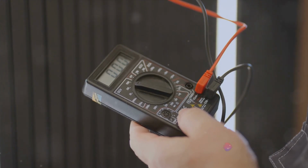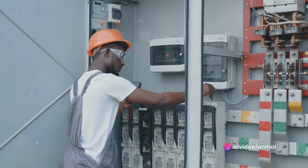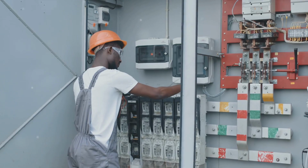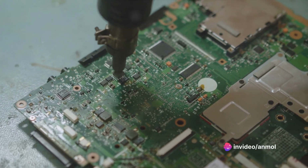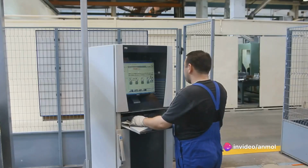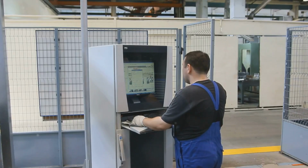Phase 1 put a spotlight on preliminary checks and the use of a multimeter to measure voltage and resistance. In Phase 2, we moved on to more advanced testing, focusing on checking the input and output power sections. Finally, Phase 3 covered rectification, where we discussed how to replace faulty components and restore your VFD to optimal working condition. Remember, practice makes perfect. With these steps in mind, you're well on your way to becoming a VFD troubleshooting expert.